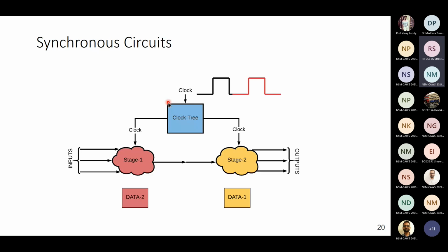Okay. So people have to rely on academic tools, which are very hard to use because there is less support and they are not very nicely tested. And so many such issues are there. So one of the major goals of the asynchronous design community is to come up with tools based on synchronous tools. Okay. So it will be an asynchronous design using synchronous design tools. That is one of the major interventions that the async community wants to first make.